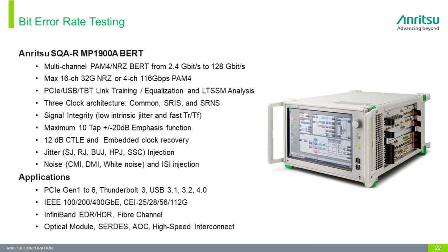It supports PCIe, USB, Thunderbolt link training and equalization, and LTSSM analysis, so it is protocol aware. It supports 3 clock architectures: common clock, separate ref clock, with and without SSC.